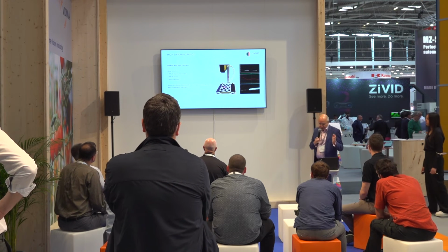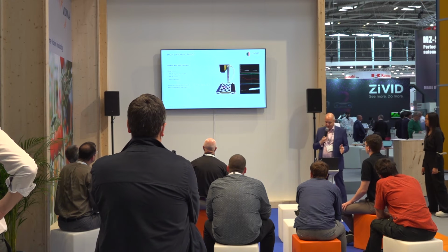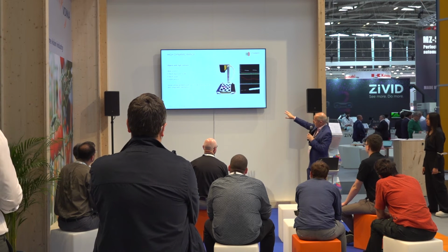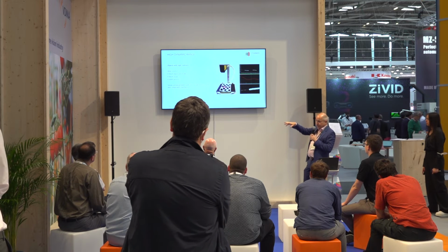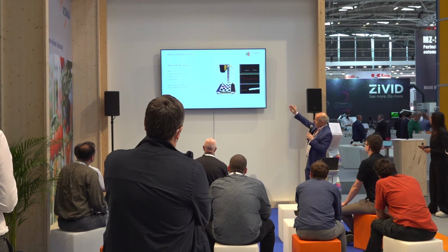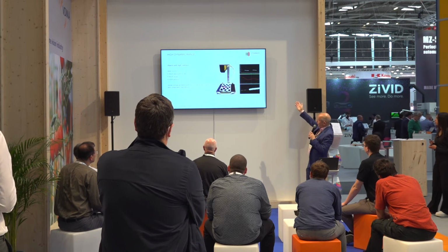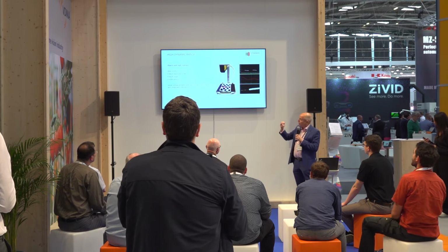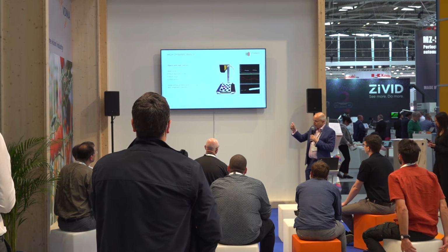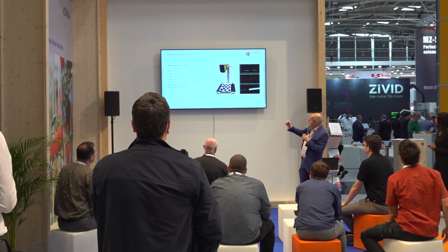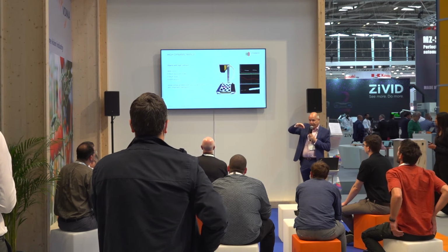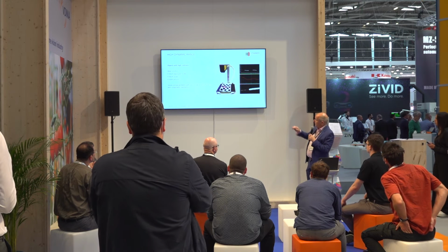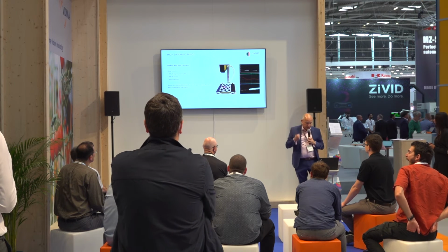Also, we have to deal with dynamic range, and things have improved massively on this over the years. But effectively, if you're looking at a surface that's got dark areas and bright areas, you will get different levels of reflection of the laser line at the top, as you can see. So what we can use in the cameras now is technology such as multiple exposures, so you can build up the image quickly, or multi-slope, where the actual sensitivity of the sensor adapts, or high dynamic range sensors.